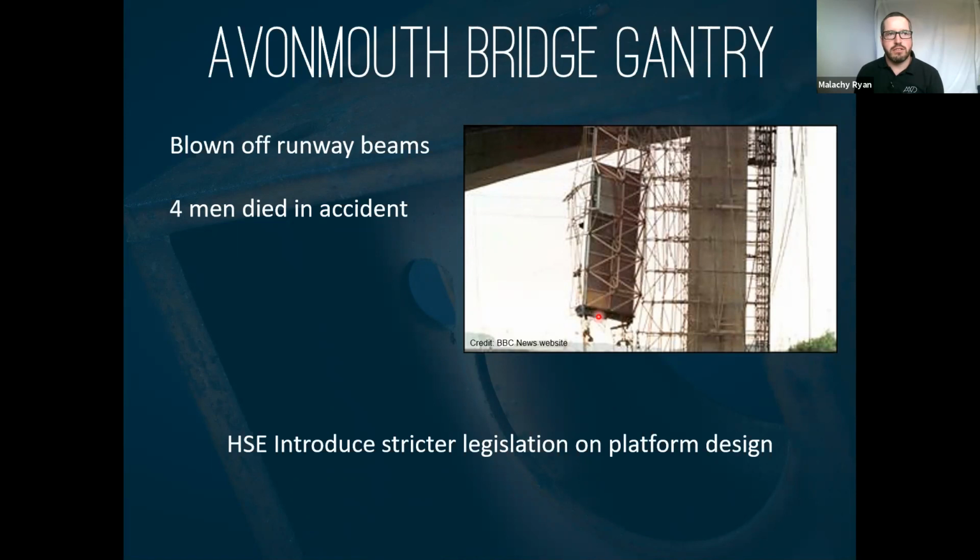end of this platform here, you can see, typically would have been held by 4 cables, 1 in each corner, and the safety mechanisms were removed. So the platform was in a gust of wind, and it rolled off the edge of the bridge beams that were supporting it on the trolleys, and it dropped on one side here. All the operatives fell to their death, and then with this big sail of wind area now, the platform was in the middle of the span, and it blew all the way to the pier, and it smashed into the scaffolding at the pier as well.